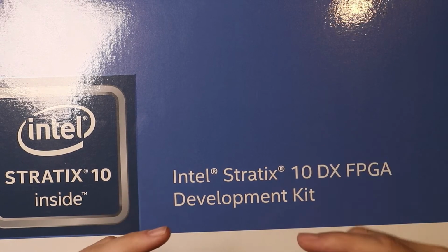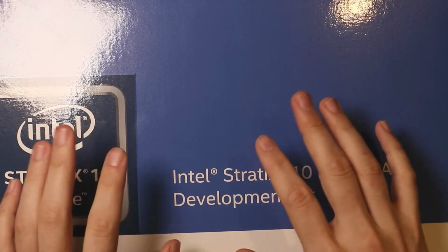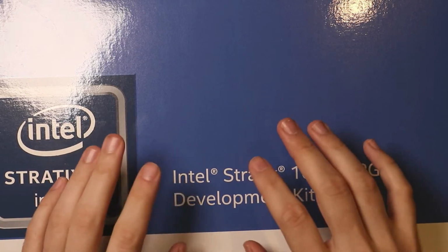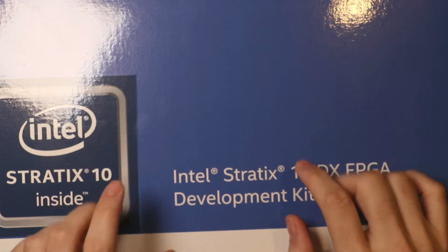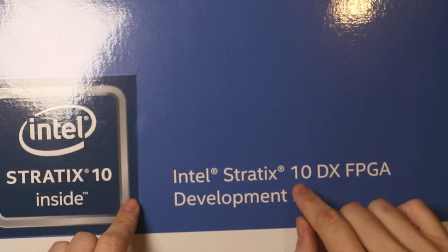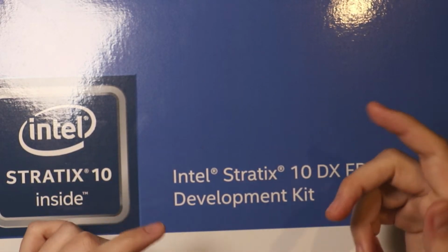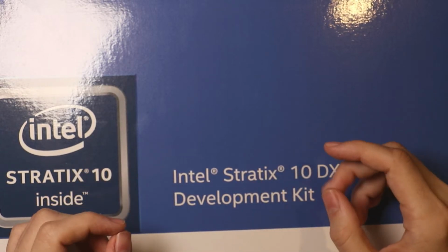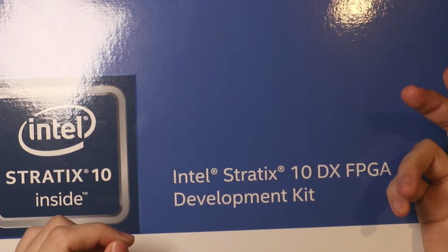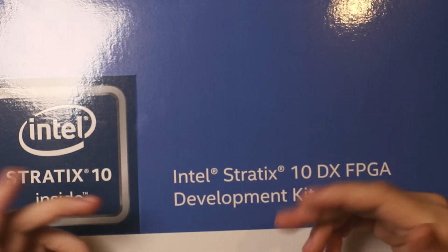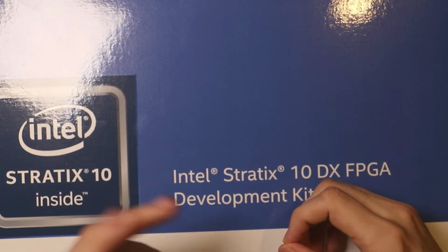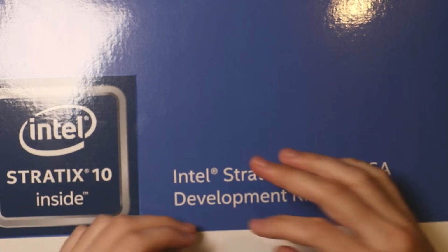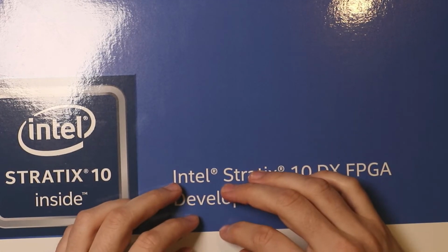Another consideration is going to be board level stuff, right? If you want particular capabilities on an FPGA, at least for a lot of stuff that's done these days, you're probably not going to be making your own board, at least for these big FPGAs. You're probably going to be buying an off-the-shelf board. So maybe you can only get boards with the capabilities that you want that have Intel FPGAs on them, for example. And that might drive your decision.